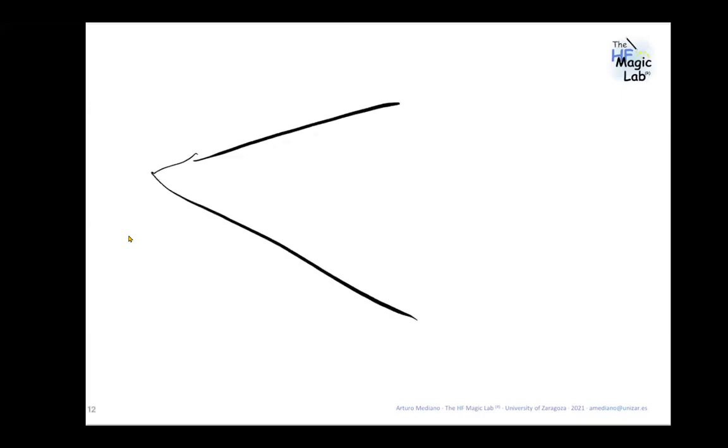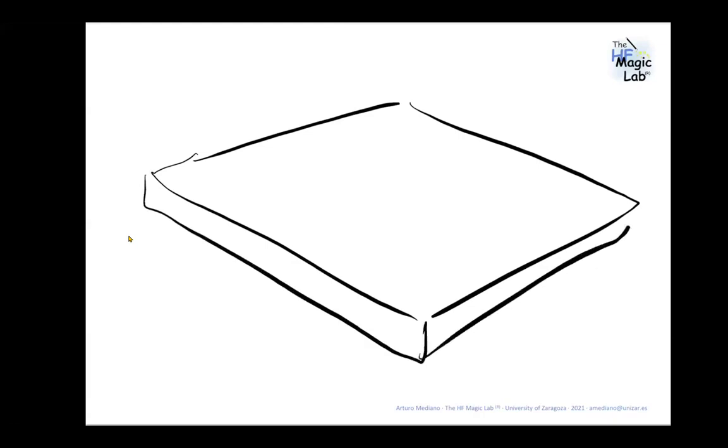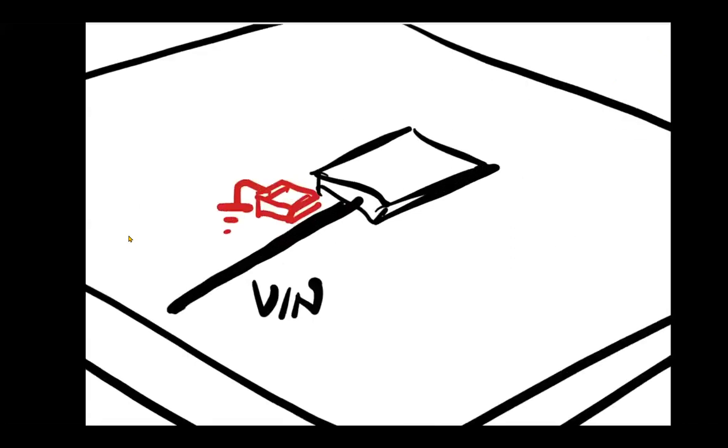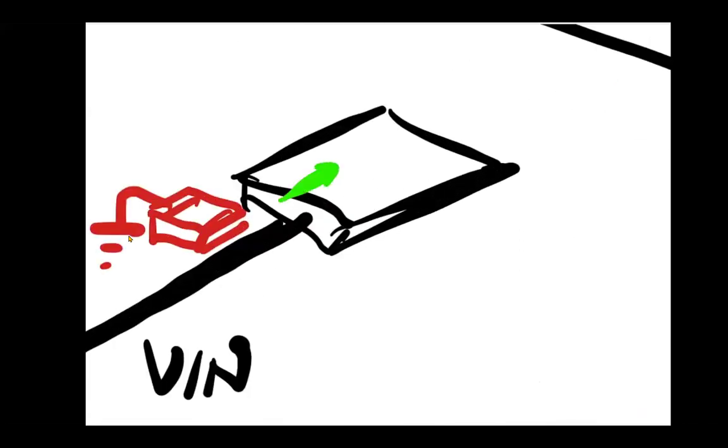If you look at one of the slides of Francesc, he was explaining that you have here the integrated circuit, and this is the V-in node. If you put a capacitor for decoupling, this is my SMD capacitor, and this net is connected to ground. The idea is that the integrated circuit is requesting switching currents, no? So the capacitor is extracting the current from the ground through the capacitor to the device under test, and then it is returning to the capacitor, no? So you have here a small loop.